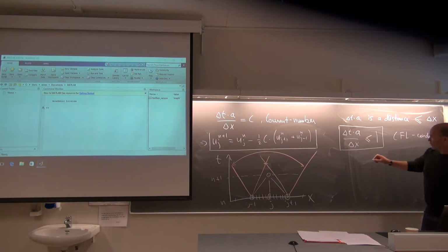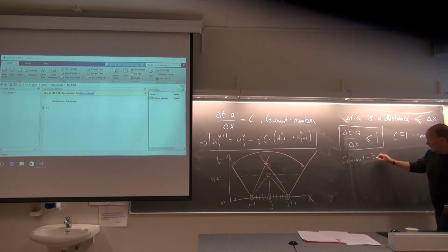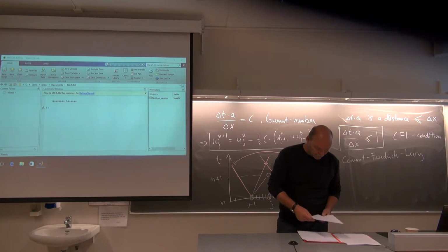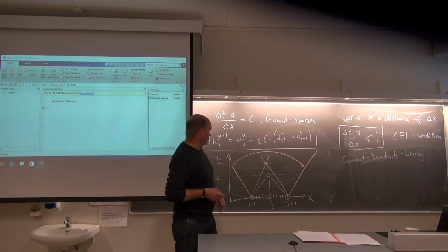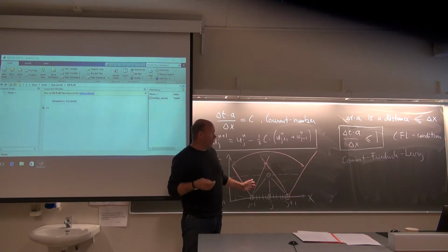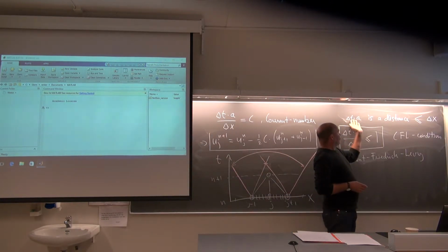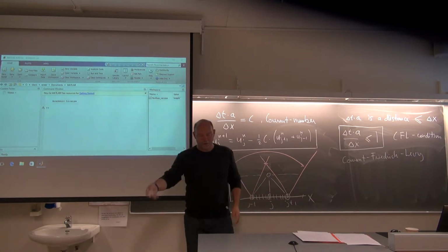And CFL stands for Courant, the F is Friedrichs, and L is Lewy. Courant-Friedrichs-Lewy condition. So here we have taken it from the hyperbolic nature of the equation. But also, you can think for yourself here, yes, it makes sense. You shouldn't let information travel longer than one single delta x during one single time step.